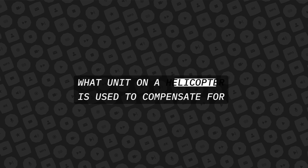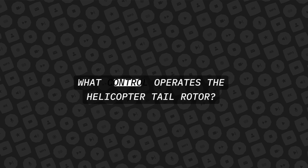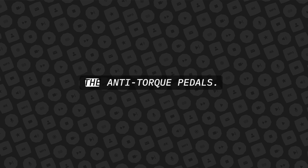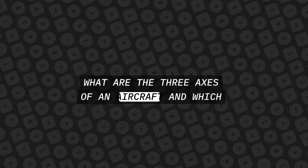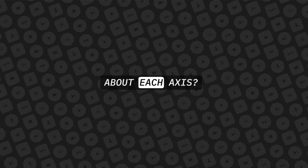What unit on a helicopter is used to compensate for torque created by the main rotor? The tail rotor. What control operates the helicopter tail rotor? The anti-torque pedals. What are the three axes of an aircraft, and which control surfaces cause the aircraft to move about each axis?